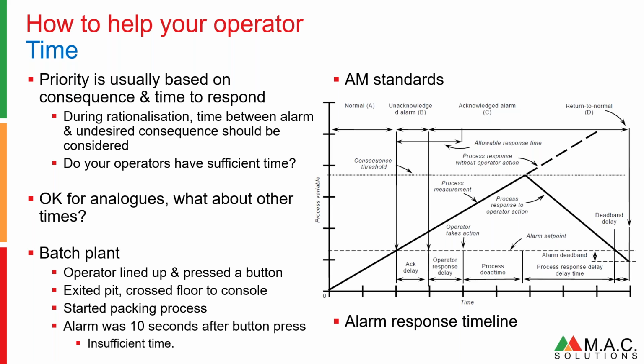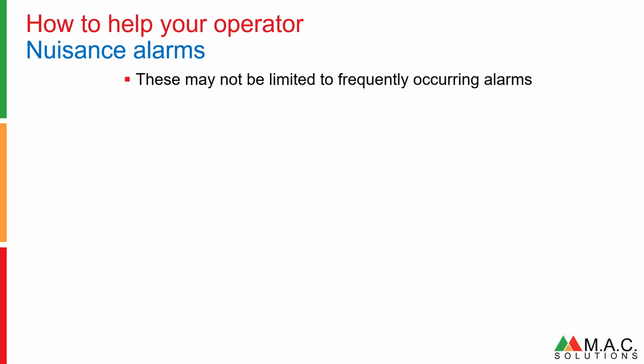I refer to a statement I made earlier. When I was looking at these things, I've told them loads of times, nobody listens, nobody ever does anything, why should I care? All of a sudden, that operator's in the mindset that there are lots of alarms happening, nobody else cares about them, why should I? There's an alarm going off as I'm crossing the plant. Do I need to react to it? Oh, who cares? Nobody else does. And that's what you do by not dealing with these alarms. That was a very, very simple thing to deal with. Not difficult, but nobody did anything. The operators told them, nobody did anything. And of course, those kind of issues happened every time they transferred a batch.